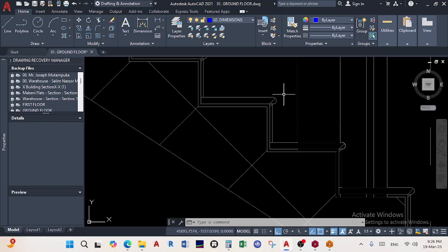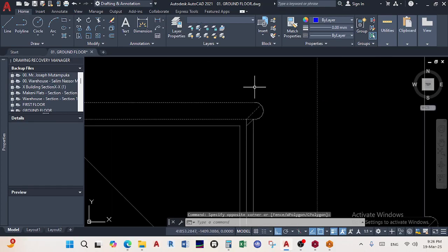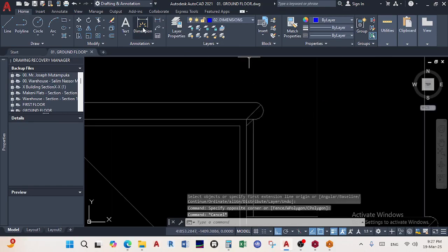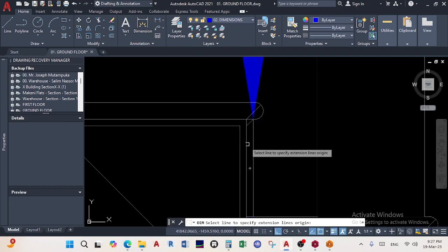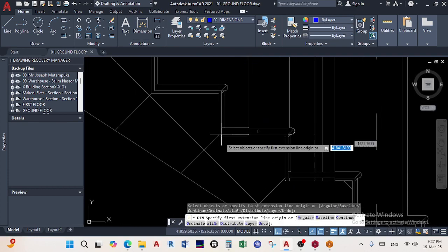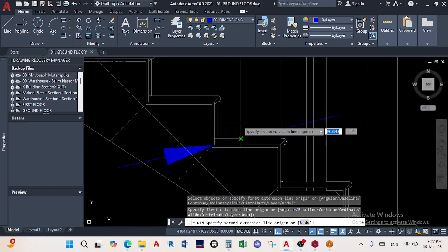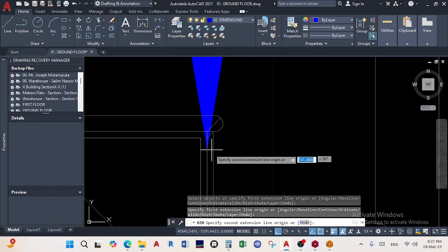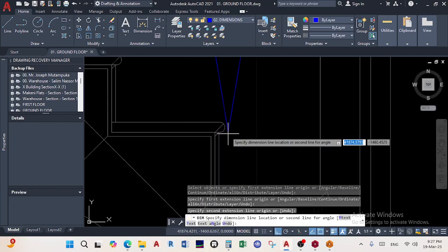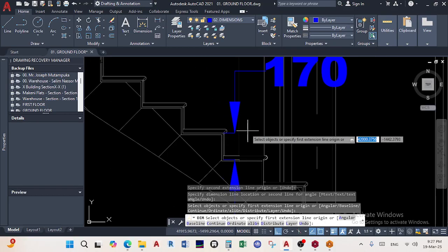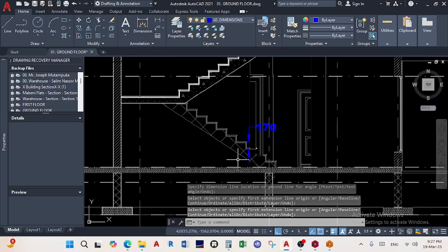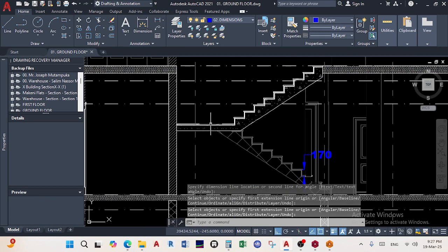But mind you, the section seems as if it's got some sketching, some toweling, whatever. So I'll measure it from there to somewhere here. This is where I think the concrete is. From there to there, it says 170 for the riser and 280 for the tread, right?